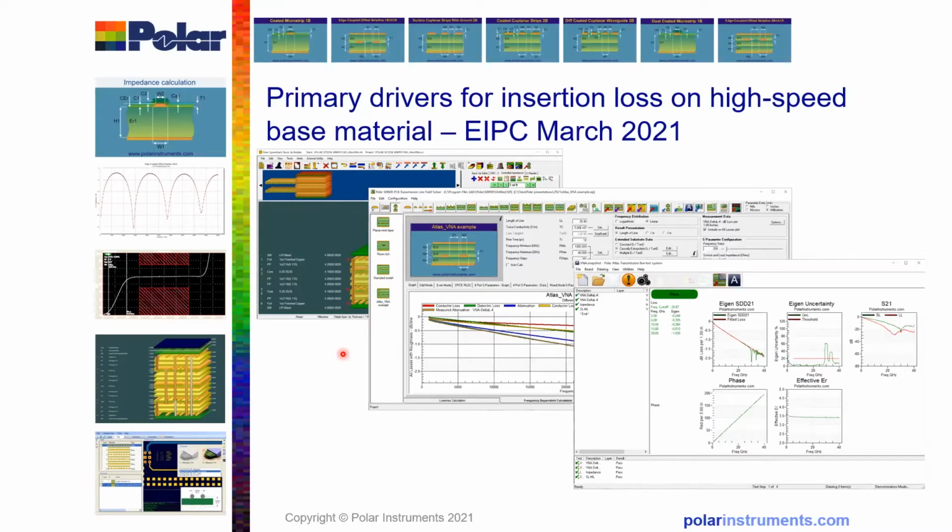And right on the first slide here, Manfred mentioned that when you're using woven glass, you can get some problems with the insertion loss. And right down here, the differential insertion loss. This was something Lee Ritchie pointed out to me, that there's a measurement here and there's a dip at around 30 gigahertz and 35 gigahertz. There are some papers that show that dip is a harmonic resonance at that frequency where the signal crosses the glass weave. So that's kind of interesting to see that on a woven glass. That's a measurement in real life showing you what happens when you have harmonic effects at certain frequencies on glass weave where you've got non-homogeneous base materials.